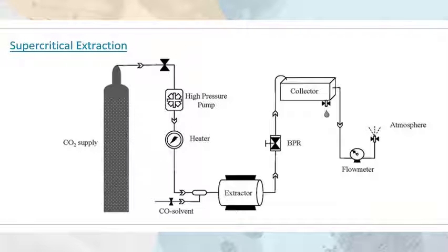Water, ethane, propane, butane, ethanol, and especially carbon dioxide have been used for extraction. The use of CO2 is preferred due to its non-toxic, non-flammable, and non-polluting properties, in addition to being inexpensive. The use of pressurized CO2 results in the absence of chemical residues in the extract because CO2 is a gas at room temperature. Not only is this technique faster than conventional or traditional methods, but it is also more environmentally friendly.